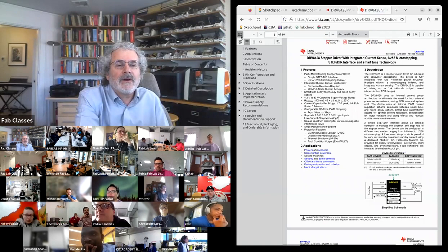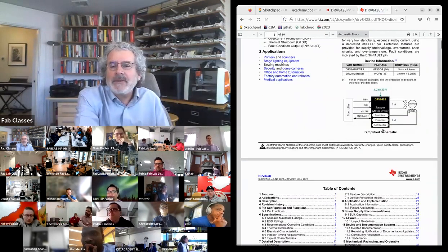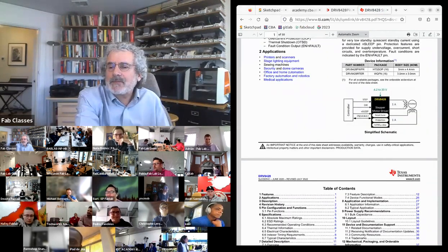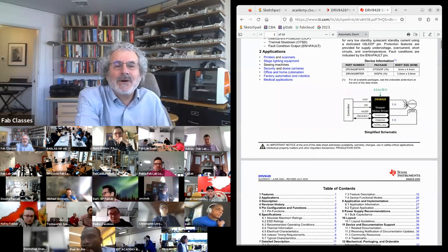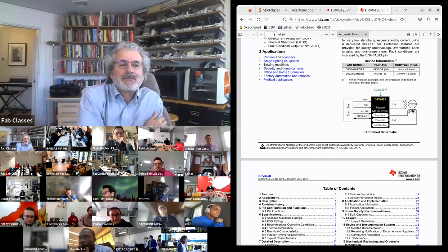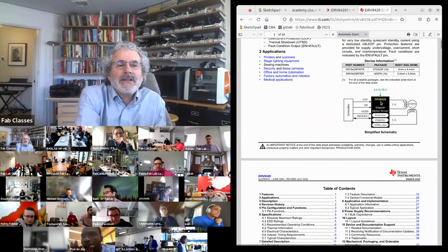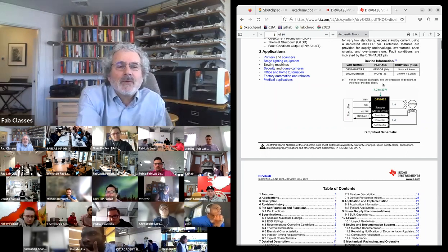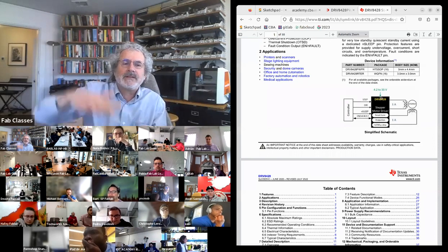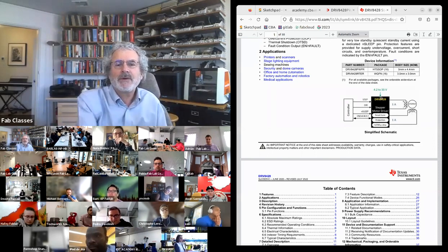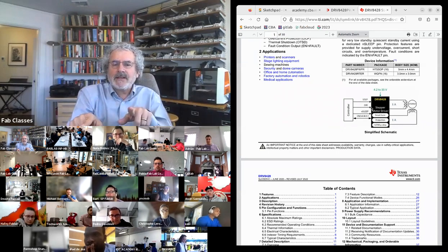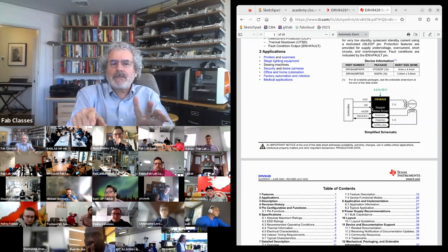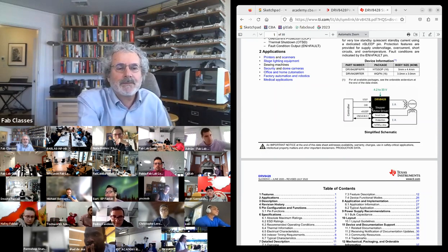So there's a lot going on here. From the outside, this goes to our stepper coils. And then there's really just, on one side, we put in the voltage, and the voltage to the motor is typically much higher than the voltage to the processor. And then there's just two pins here going in, step and direction. Step says, I want you to make a step, and direction says which way to turn.